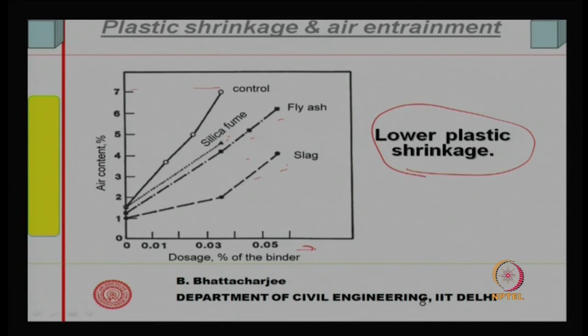So, it reduces the efficiency of air entrainment. The fine particles, the cementitious particles which you add, reduce the efficiency of air entrainment. So, the volume of air that gets entrapped, or rather entrained, is relatively less in these cases. So, this is another effect.